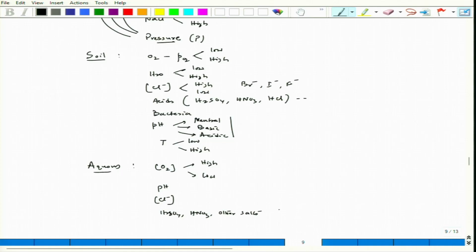So, the electrochemical circuit that we talked about in the previous lecture should be complete, but that circuit will have difficulty in completion. That means the resistance path would be so high, the resistance polarization would happen, and then it will lead to a very low degree of dissolution. Fine. So, whenever these salts or ions are present, that is when you can have the effect of conductivity.